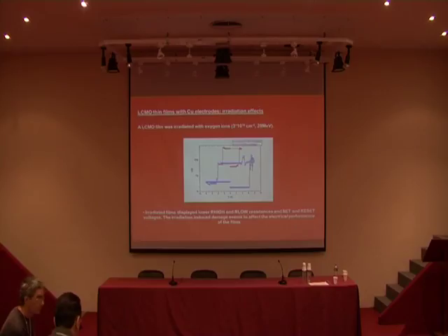Yeah, I do not understand the bipolar once the filament is completely formed, because you have an ohmic contact. If you measure bipolar, you will see bipolar. No, but I do not understand which is the mechanism behind, because you don't have enough electric field to move anything. I think it's a filamentary regime associated to the migration of copper or silver ions or atoms on the oxide. Okay.